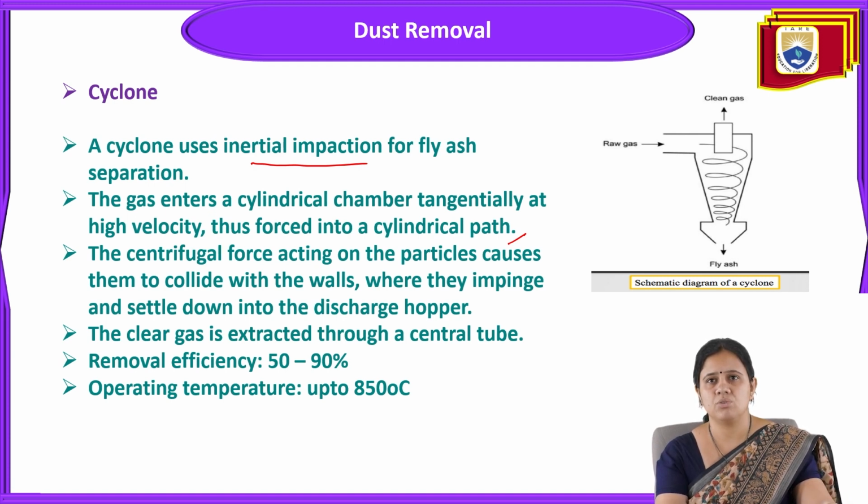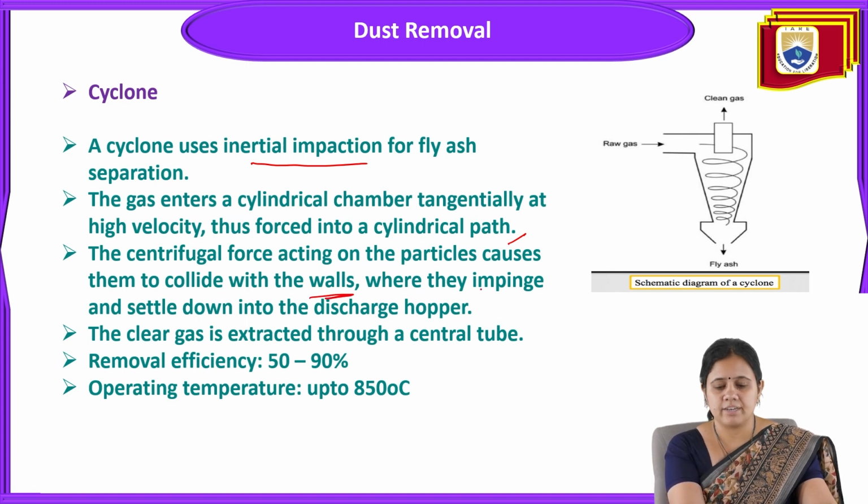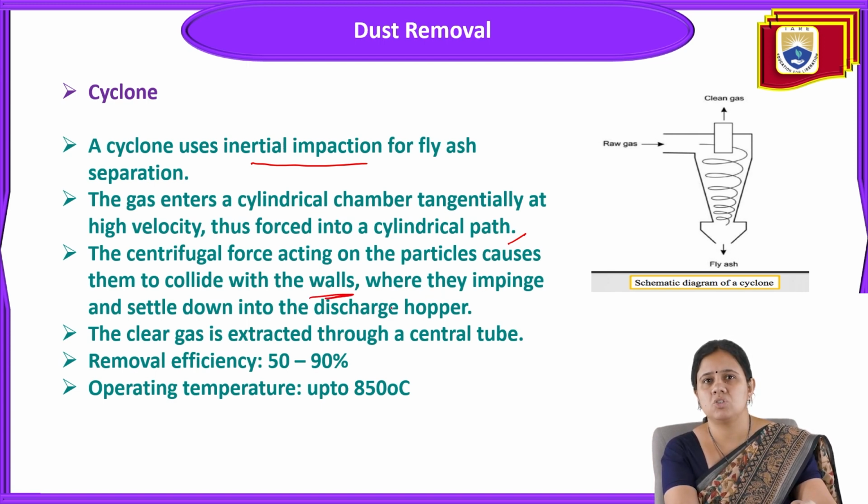The centrifugal force acting on the particles causes them to collide with the walls, where they impinge and settle down into the discharge hopper.